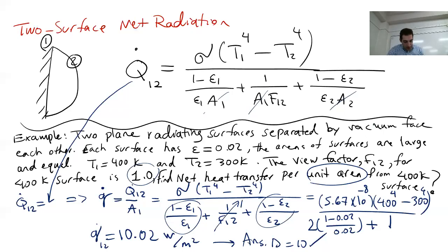Now, next one is net radiation heat transfer between two parallel plates, Figure 21.2, with radiation shield. Okay. Now, sometimes to reduce the rate of radiation, they put those shields in between, so it can reflect maximum to the source of heat, so the other side remains cool. Now we're going to talk about that, which is a very typical case for a question.